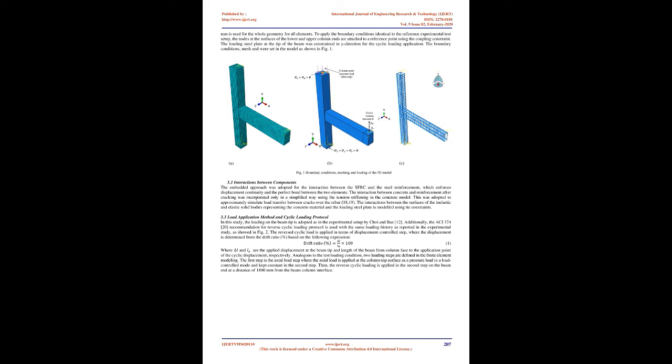1. Introduction. Moment-resisting reinforced concrete frames are assemblies of beams and columns connected by beam column joints. These frames should have adequate ductility, strength, energy dissipation, and stiffness to resist the seismic loading without collapse. Several studies [2-7] have established that SFRC is capable of improving the seismic behavior of reinforced concrete structural members, such as shear walls, beam column joints, and axial members subjected to seismic loads.